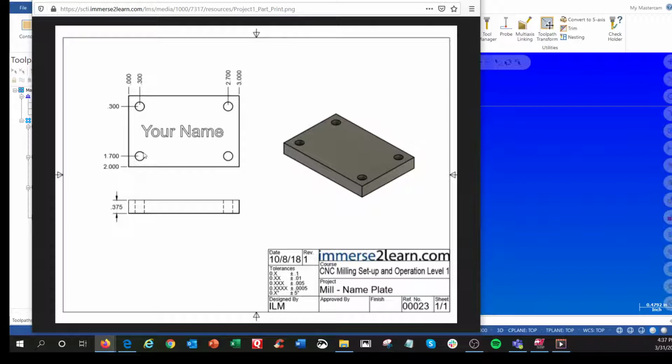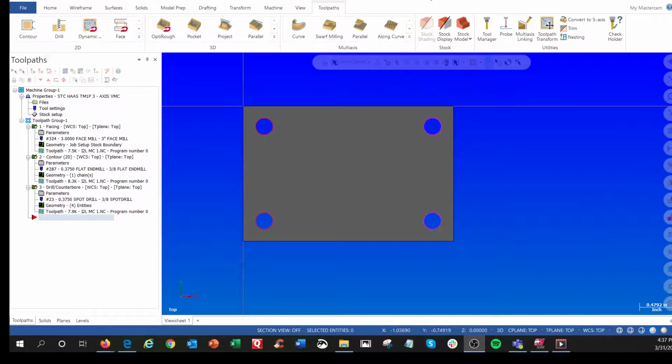Now, how are we going to machine this thing? We need to face mill the top or end mill the top. I think face milling or fly cutting would be the best method to do the top. The engraving we're going to worry about later. We're going to machine this rectangle here, probably using a 1/2 inch or a 3/8 end mill. And then we have to put these holes in, and they haven't given us the specs on the holes yet, so we're just going to spot drill them for now until they get the specs and we can add in the drill later on.